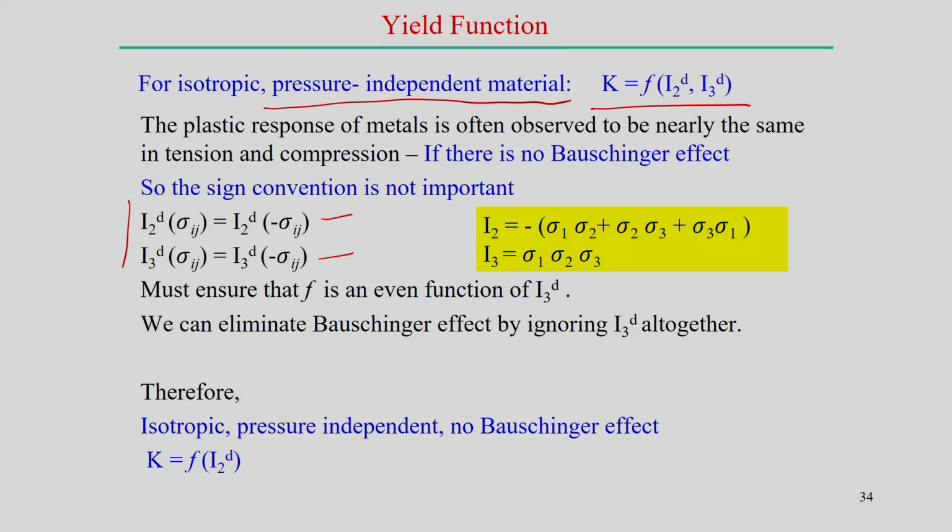Since the compressive yield stress has the same magnitude as the tensile yield stress but a different sign, mathematically we can say the function should be an even function.